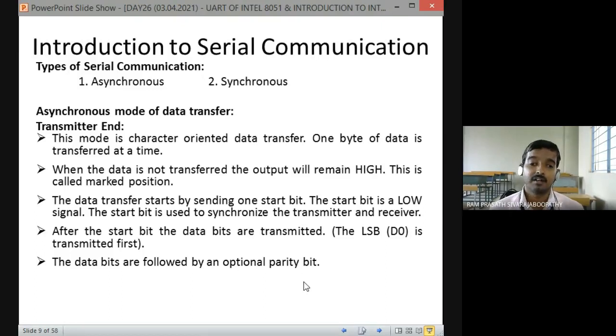Whether we are going to do a parity check or not, both the transmitting and receiving devices have to agree on the rules. If the transmitting device sends a parity bit, what must the receiving device do? It must perform the parity check. The 9th bit is going to be received as a parity bit. Now you can understand. 8-bit is the universal thing. Usually the 9th bit is a parity bit. Is it clear to everyone? Yes?